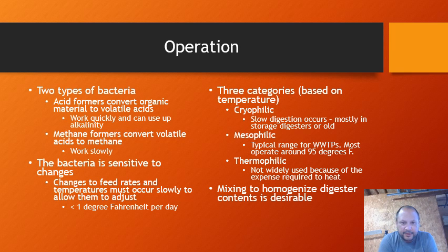or stuck digester. So an important lab test to do in process control for anaerobic digesters would be your volatile acid and alkalinity testing. And then there's a volatile acid to alkalinity ratio that you need to maintain so that you do not get too many volatile acids disrupting the anaerobic digestion process.